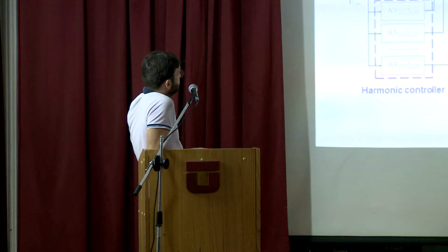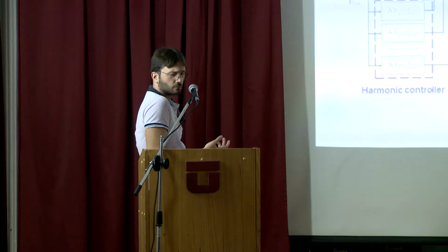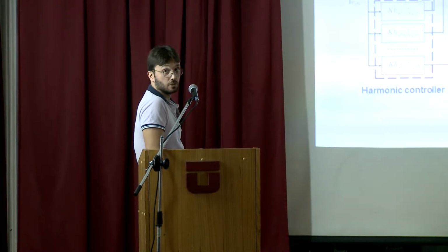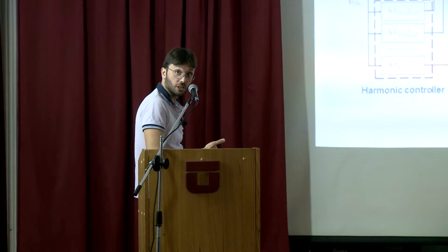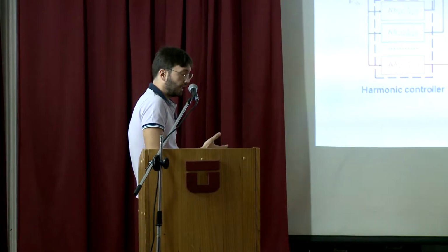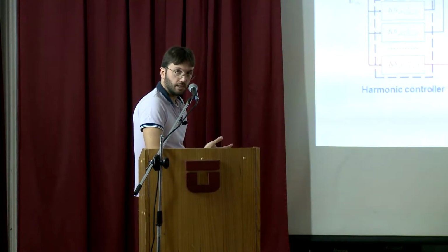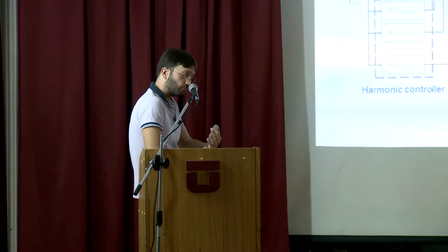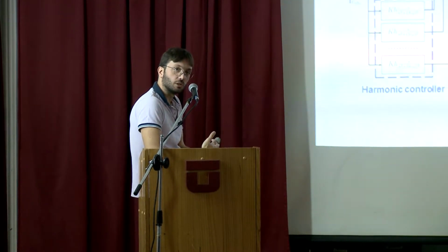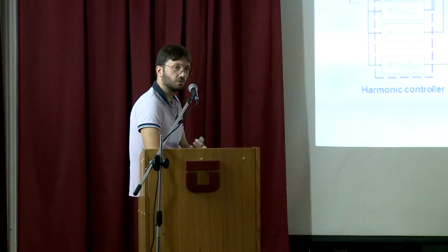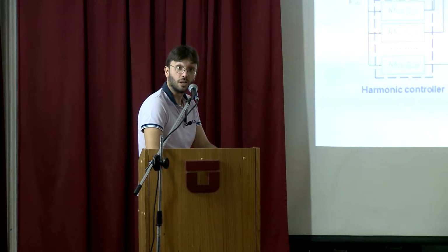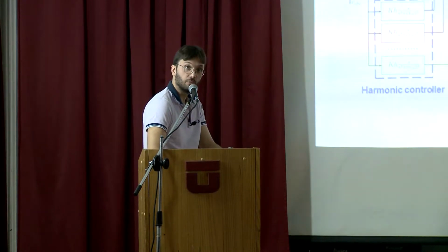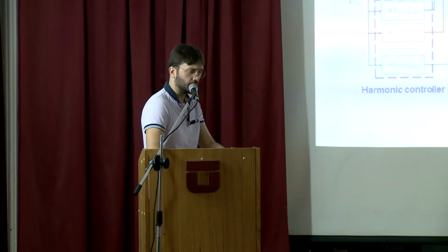Okay. Then, for the low voltage converter, what we saw yesterday was a simple proportional or proportional integral regulator. Yeah, this is really one of the basic steps. But once we really start digging into how a low voltage converter should be done, there is a vast literature related to uninterruptible power supplies, because this is what a UPS actually does: it creates some stable grid supply when you have no grid.